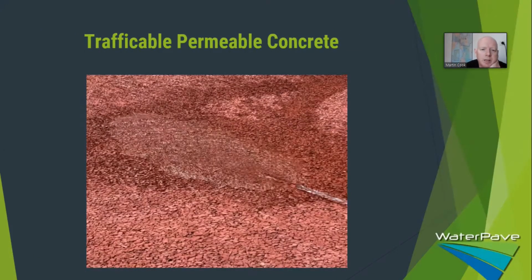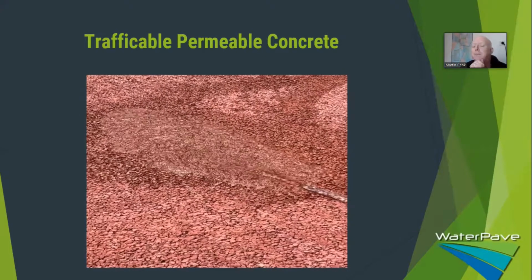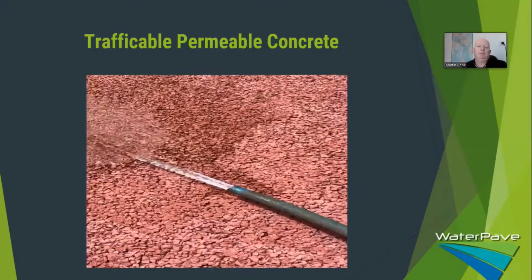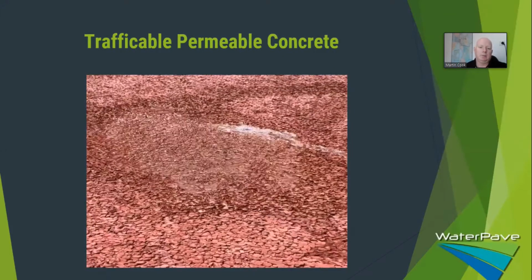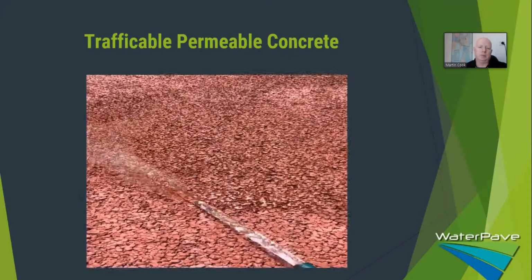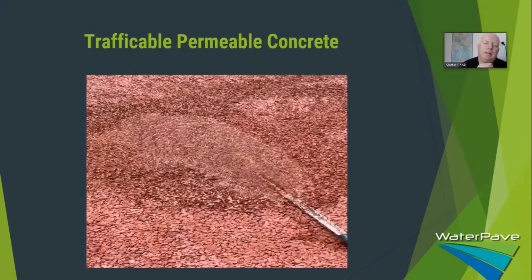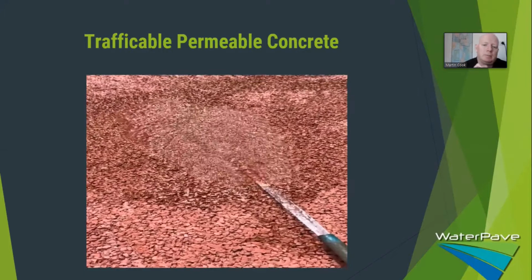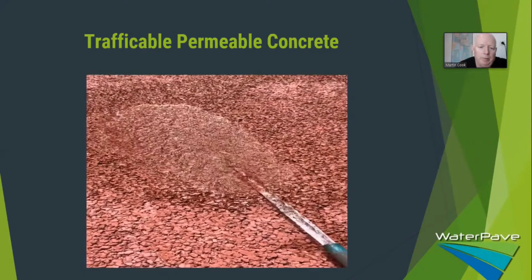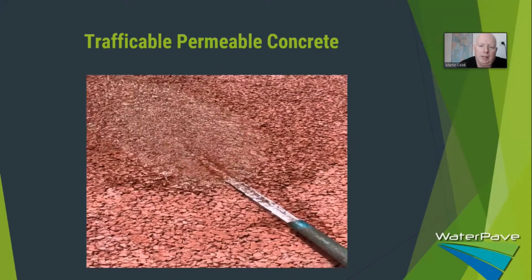It's another small video here of the ability for the water to absorb. That was a red oxide colour actually in the cement. So if you use permeable concrete, you can actually have an oxide colour put in the mix prior to it coming to site, and it doesn't really matter what colour you put in it, you just treat it like normal concrete. Again, the mix design is imperative, that has to be correct.